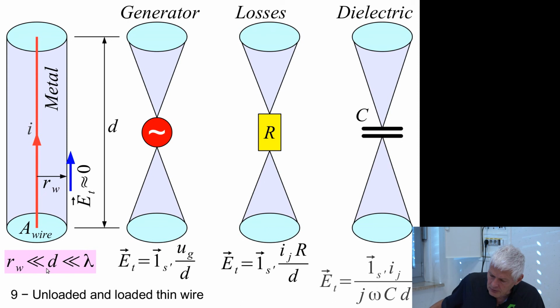With the current software we are going to use today, the NEC2 software, it is required that the radius of the wire should be at least 8 times smaller than the length of the segments we are using. And if we accidentally define segments that are too short, the software is going to warn about that: you are outside our approximation.